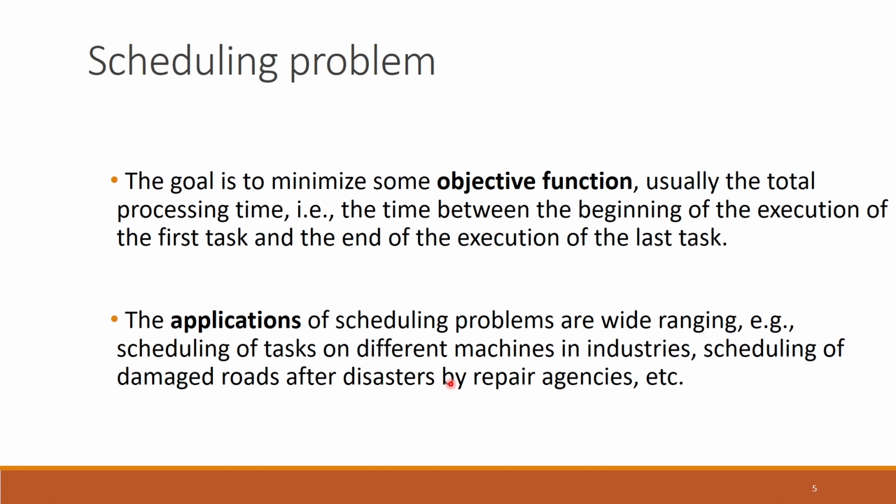Since the blocking of every road creates some congestion on the network, the sequence in which you unblock these roads might have an effect on how much final travel time is experienced by the network. So in that kind of problem, determining the sequence is important.